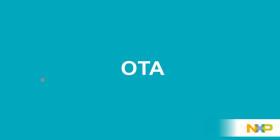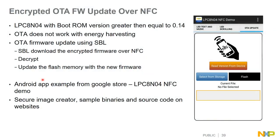The last part of this one is OTA. We have implemented an encrypted over-the-air firmware update over NFC. Just keep in mind that the LPC804 has to have a boot ROM version greater than or equal to 0.14. And OTA doesn't work with energy harvesting. It has to be battery powered or USB powered or something like that.